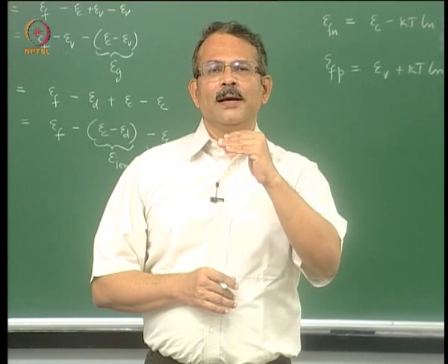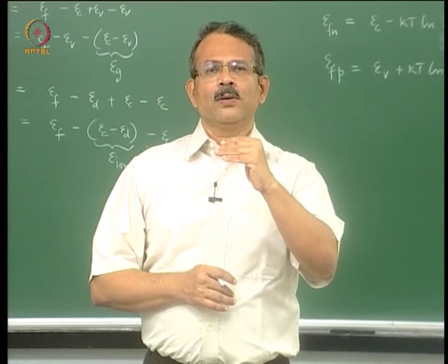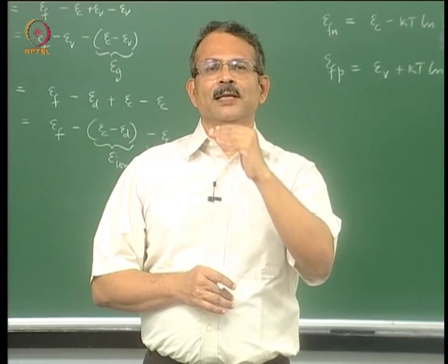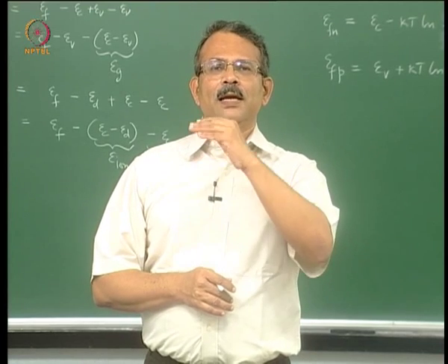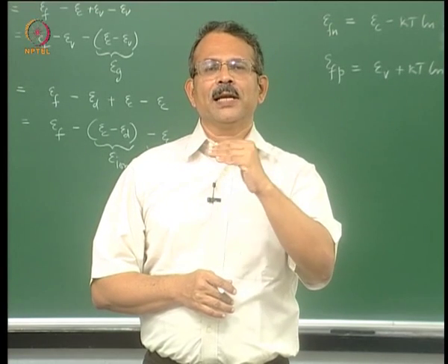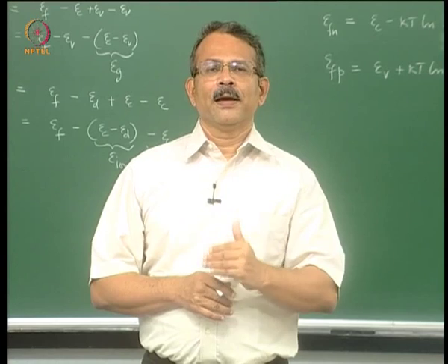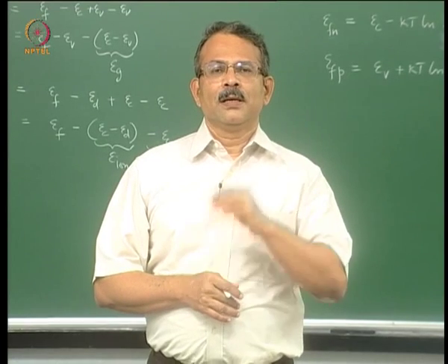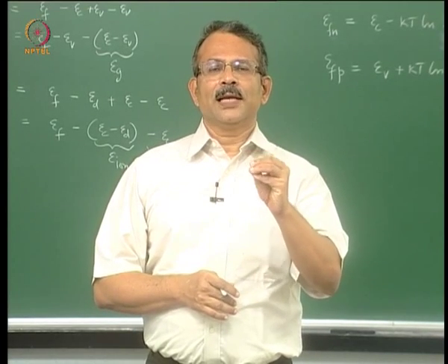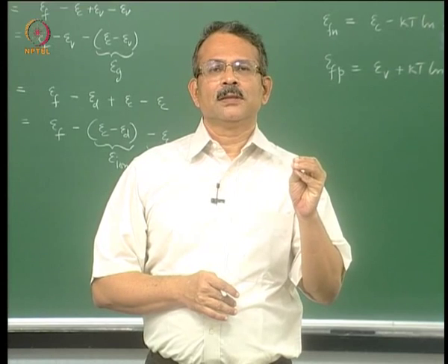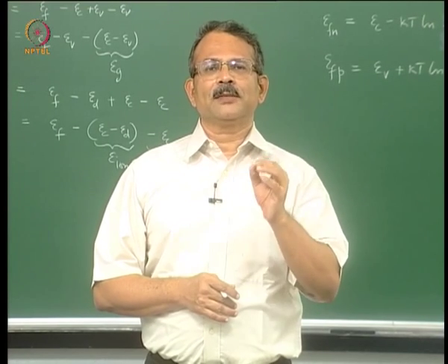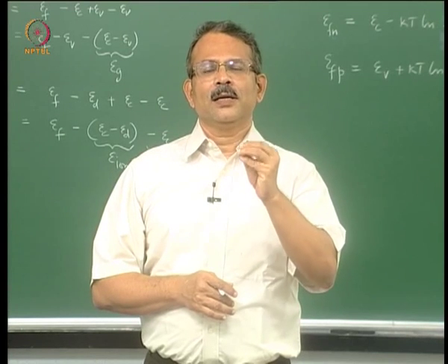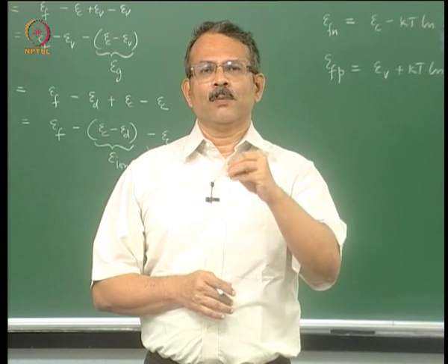We also showed how the energies associated with impurities can be shown on the energy band diagram. Basically, impurities and defects add additional energy levels within the energy gap. The E naught reflects the electrostatic potential and the slope of E naught reflects the electrostatic field experienced by an electron touching the semiconductor surface from outside.